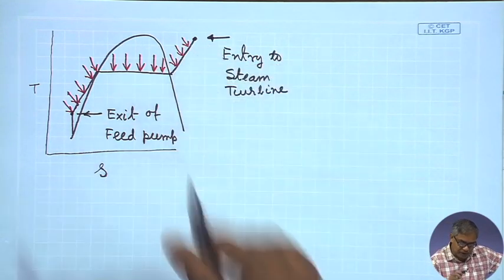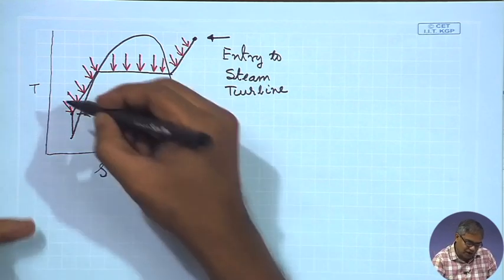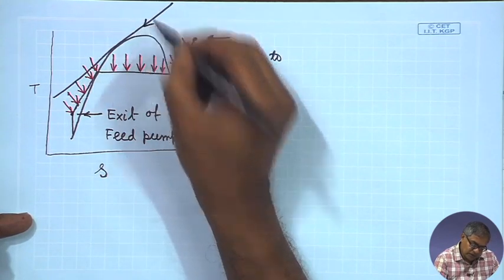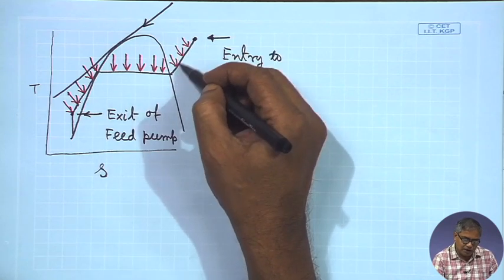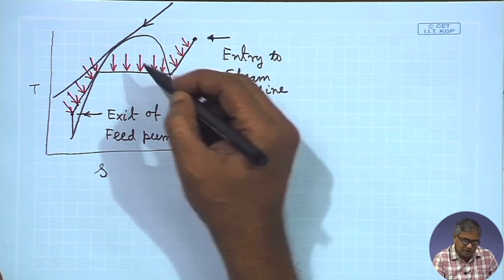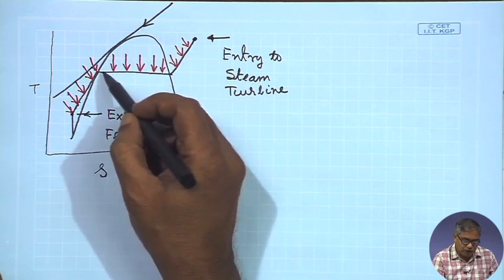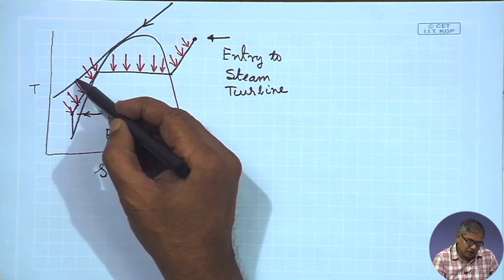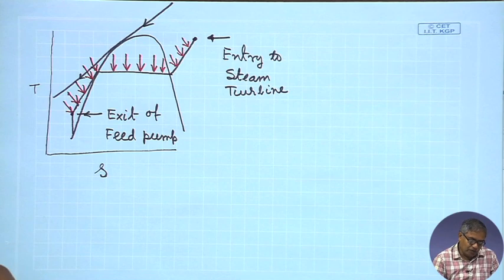Here you see how the gas temperature reduces, as I have shown earlier. The highest gas temperature should encounter the superheater. Then when it is a little cooler, it should supply heat for the evaporator, and when it is much cooler, it should supply thermal energy for the economizer.